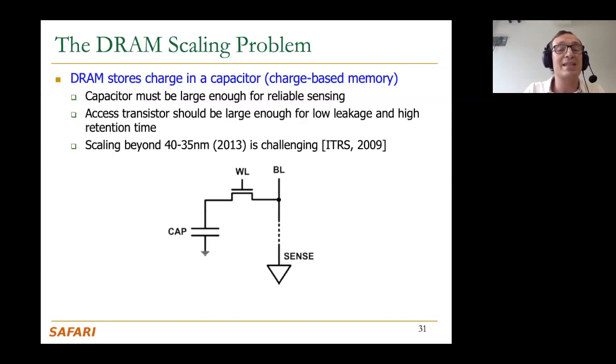To be able to make this capacitor work, what the DRAM manufacturers are doing, at of course low storage area, that's important, is really etching into the wafer a lot in a three-dimensional fashion. It's not exactly a three-dimensional stacking technology. It's really a single wafer. What they're doing is really etching the single wafer. And at some point, this may become unsustainable, right? Okay.